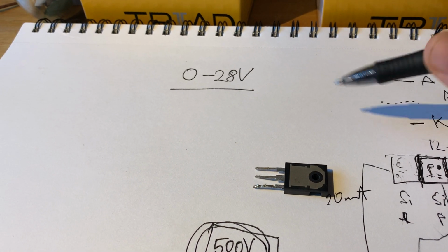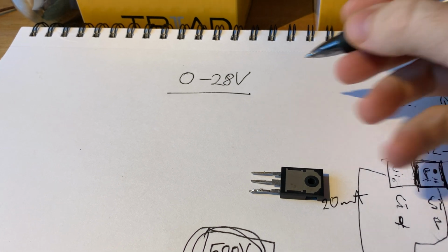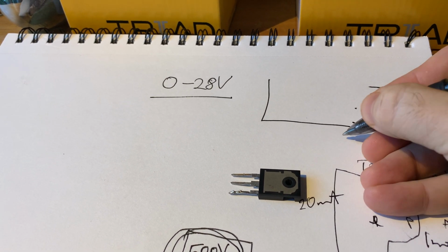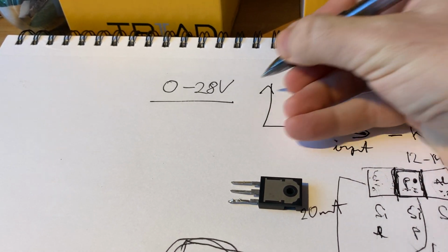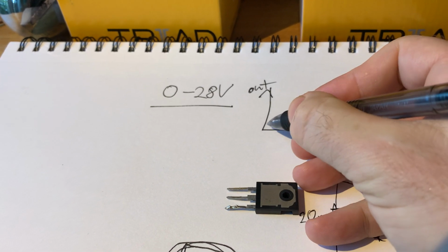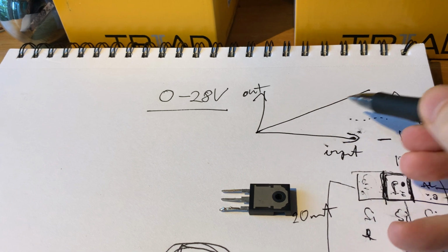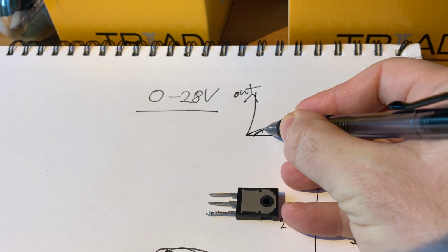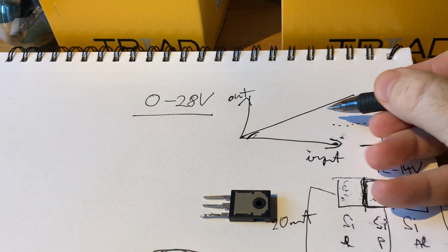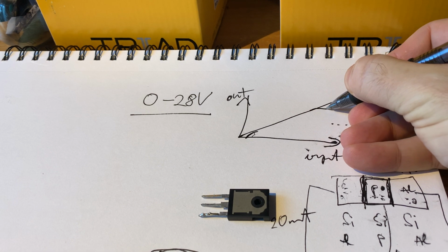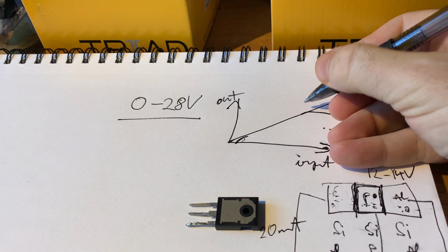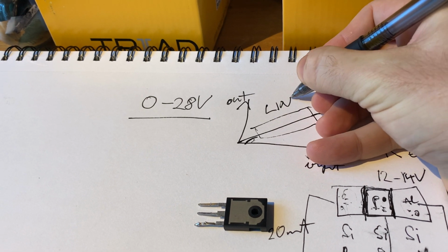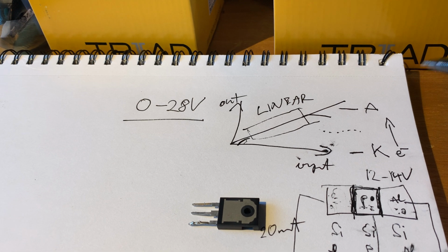However, there's something called nonlinearity. It means that all devices, if we look at this, this would be the input signal, and that's the output. As we increase them, we should expect that with greater input you get greater output. However, due to the nonlinearity, when we are in the small signal range, it falls off, and we are not getting a linear region there. And when we are at the peak power, it cannot handle any more and it will peak out. So this region in between the two, right there, is called the linear range. And that's what is useful for your audio.